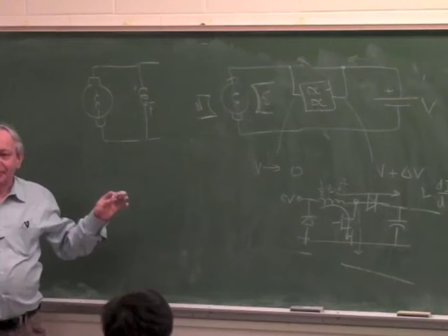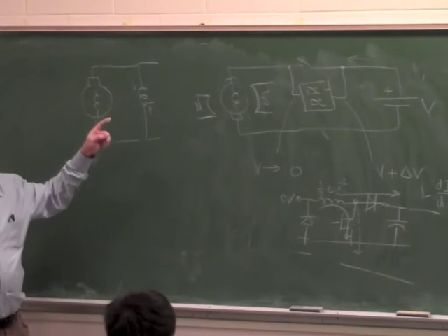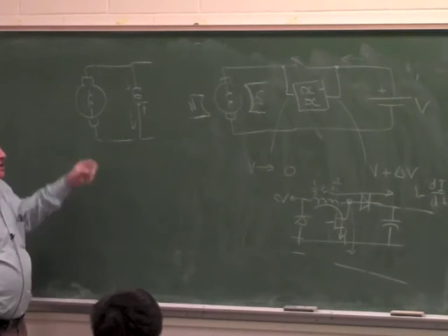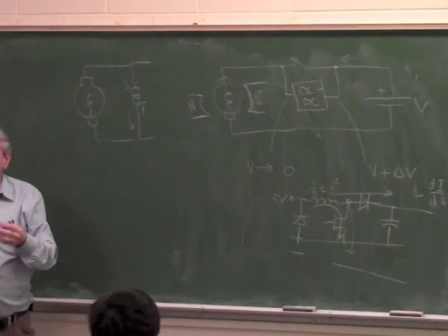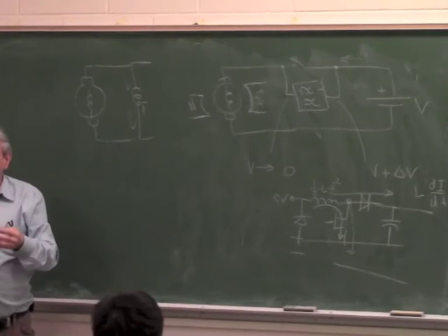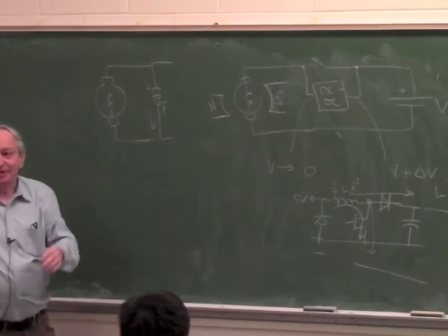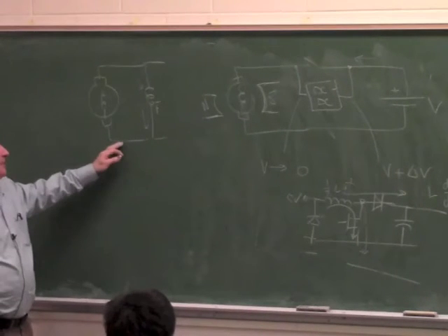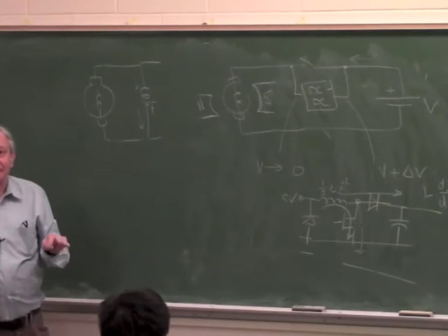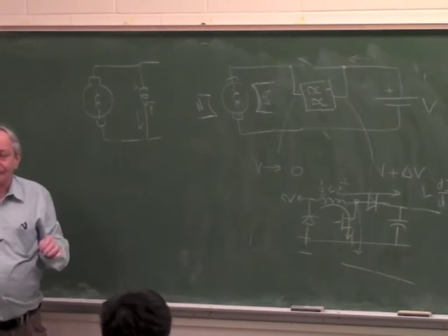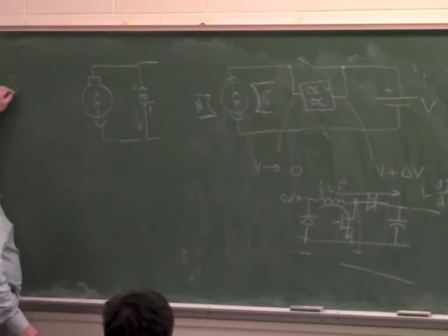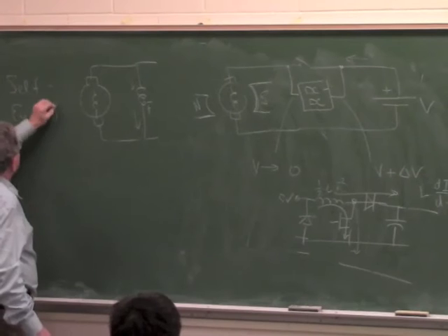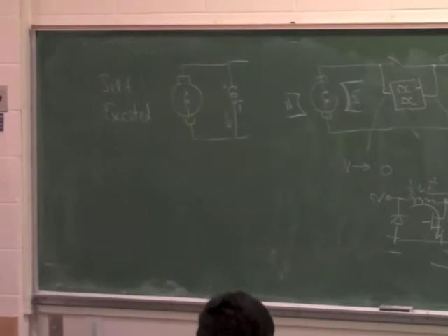Is that clear to everybody? Because it's a positive feedback. As you recall, in a motor, the field current is much smaller than the armature current. So a motor is actually an amplifier. If you take any amplifier and close it with positive feedback, it will ramp up to saturation instantly. So is that clear to everybody why this will work as a generator even if it has no magnet? Good. So that's called self-excited. Okay, good. Now, it's very easy to understand.